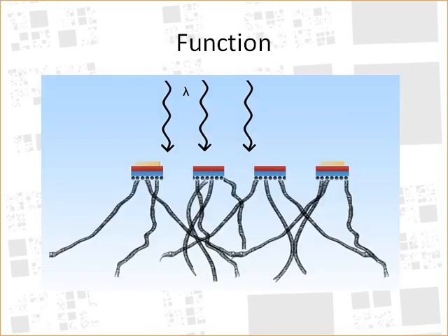In use, the freestanding inorganic neural network is placed in an electrically conductive solution, which also has non-conductive surfactants present. When the voltage level of a given photodiode or nanotube rises above a certain point, the surfactant preferentially adheres to this site, preventing electrical loss from the photodiode to the ground of the conductive solution.